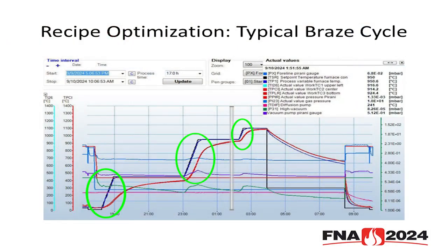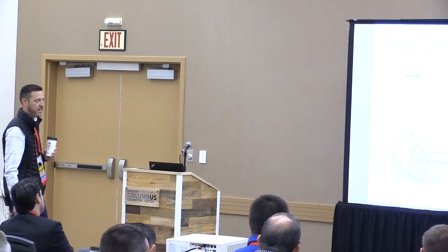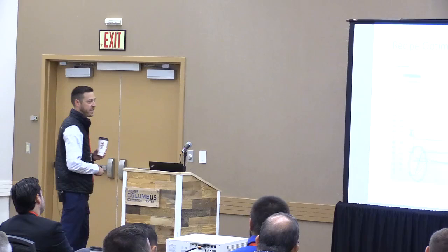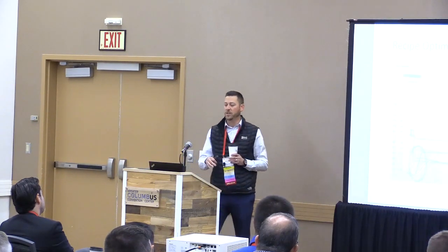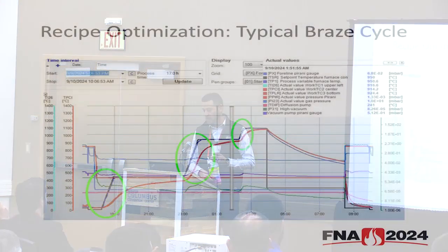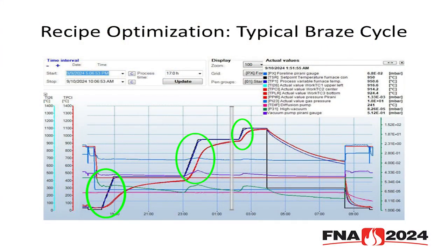They're giving it a little bit more grace on the first one because we're not anywhere near a critical temperature. And then on this last one, they're going to go to their critical temperature, so they want the parts as evenly soaked in as possible and as close to set point as possible, which is why it's a little bit tighter there. But that's something they can do. They should lift that up to a higher temperature, and to shorten that duration, maybe give it a bigger deadband before it applies heating to the next segment. And then that second one is pretty appropriate, and then they're going to about 2,000 degrees for that final step,